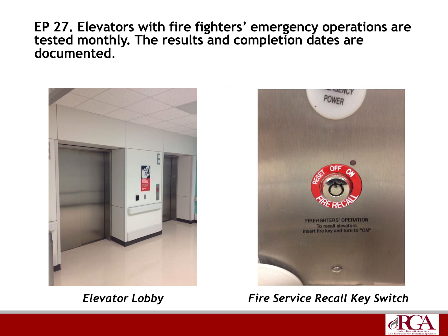When you do the intercom call, though, the emergency call, whoever is on the other side of that call needs to be able to tell you where you're at, which elevator car you're in, whether you're in the service elevator, car number 4. Obviously, they might not be able to tell you right off the bat what floor you're on, but at least they can tell you what car you're in. And so you definitely want to verify that monthly. Now the elevator recall is also integrated into the fire alarm system, and that's a separate check that's checked annually. This is just a monthly phase 1, phase 2 firefighters check.